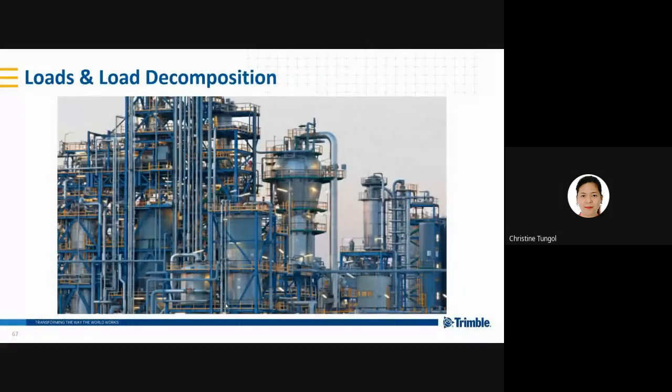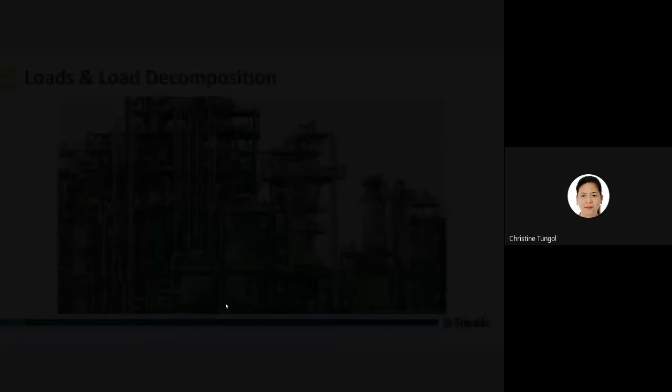Loads generated through open structure wind load are applied to the relevant members or items in the relevant wind load cases for the wind direction being considered. All full uniform distributed loads relating to open structure wind load can be directly applied to the members, line and area ancillaries, or forces applied to equipment are decomposed as any other loads in Tekla Structural Designer.